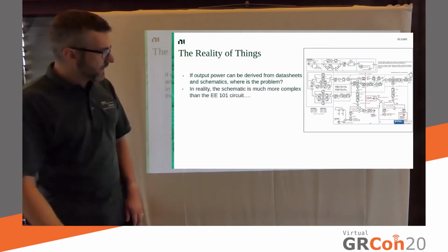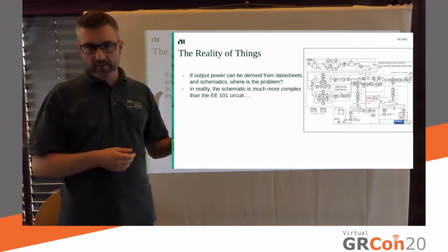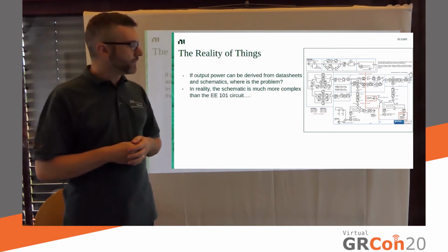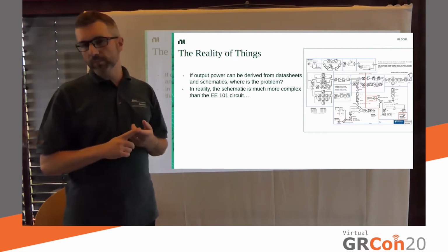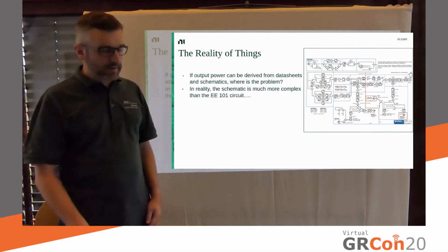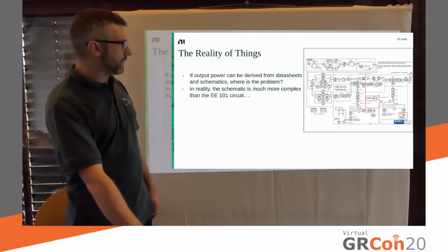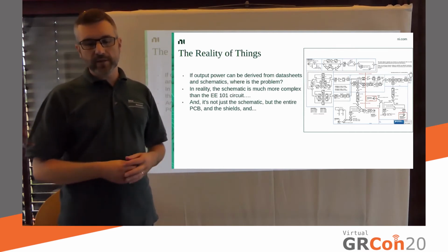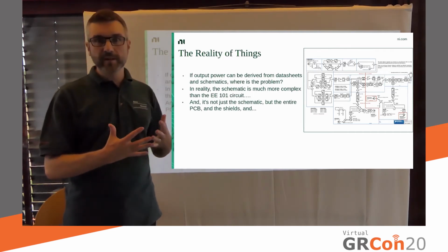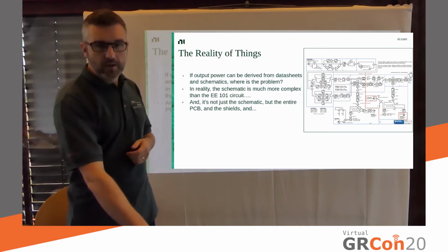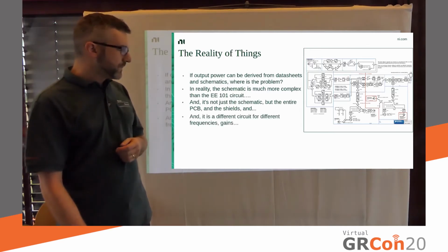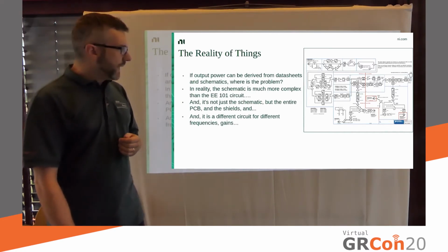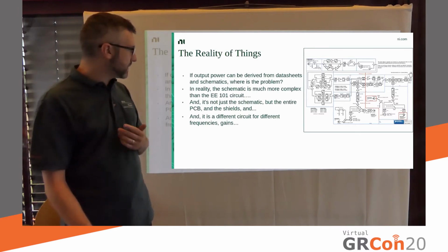Well, no. Because in reality, schematics look much more difficult than the one that we just put on the slide or on our pad, because that's something you only see in EE 101. In reality, you don't have 0 ohm traces, and you have amps and whatnot. Also, frequency-dependent behavior. Plus, the schematic is really just one piece of the equation. What you also need to know is what the actual PCB looks like, and the mechanics and everything, to properly calculate what's going on. This is the TwinRx daughter board schematic, or at least a simplified version thereof. And it also has frequency-dependent behavior, so that's something else we need to factor in.